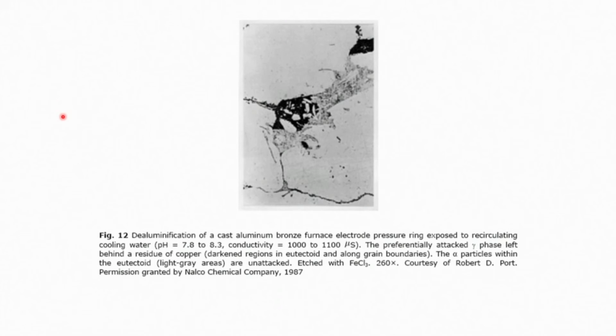So there is microgalvanic cell formation between the grain boundary regions and the grain regions, and the adjacent grain boundary regions get depleted in chromium. The problem starts at the adjacent boundary regions, and after the corrosion is over, you will find that failure starts from the adjacent boundary regions rather than the grain boundaries.